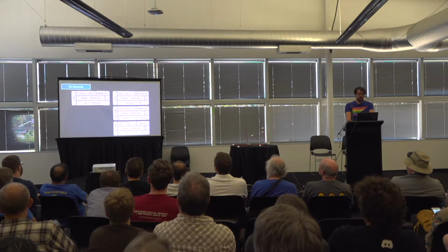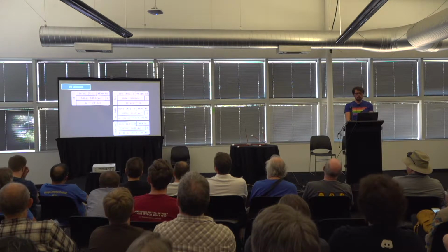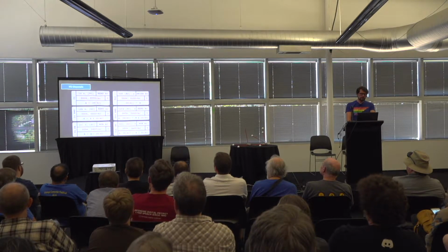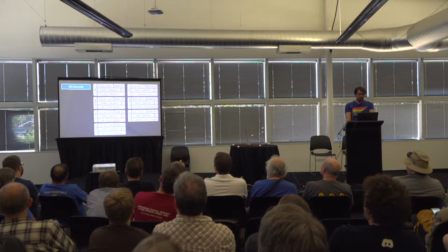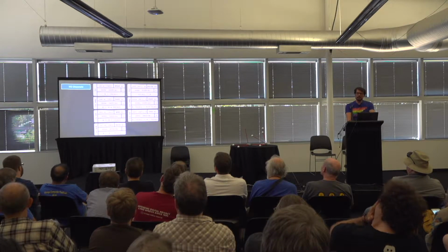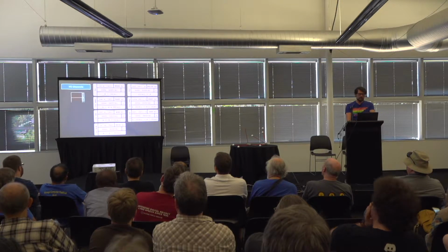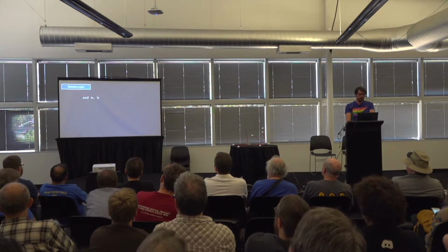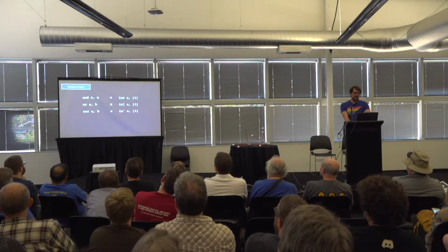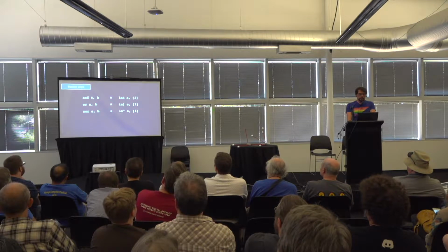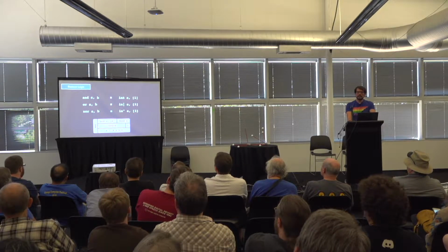So I/O instructions can work on the whole word or do Boolean operations on them: and, or, and XOR. To make the Boolean operations also usable between registers, channels 1 and 2 are aliased to the B and LR registers, which allows for instructions like AND A, B or OR A, B, XOR A, B. For AND, there's also a dedicated instruction that works on A in memory.